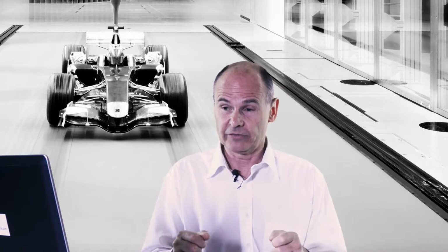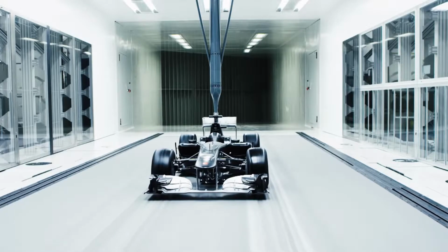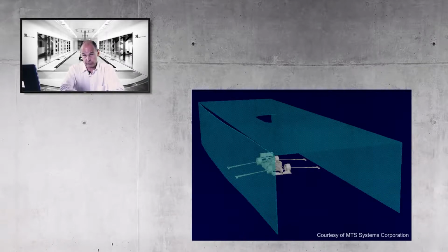Then there is another type of technology which is called contoured wall, which almost nobody uses, because a contoured wall wind tunnel would make the shape of the wind tunnel the same shape as the air would form if your test body was permanently this type of test body, with very minor changes. The air would form a certain natural shape in free stream if you're just punching a vehicle through the air, and you make your wind tunnel form that shape. But if you, for example, want to yaw your model or your car, then you would need a different shape of wall.